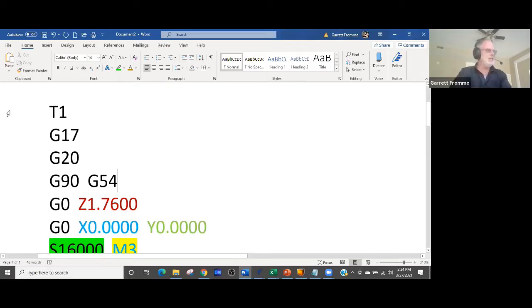You'll see a T, which stands for the tool number. For any of us, that doesn't matter. What that stands for is if your CNC router has multiple tools in it, where the CNC router actually goes and does its own tool change. We have to stop it. We have to actually change our tool or our router bit. So this is really not a relevant thing.